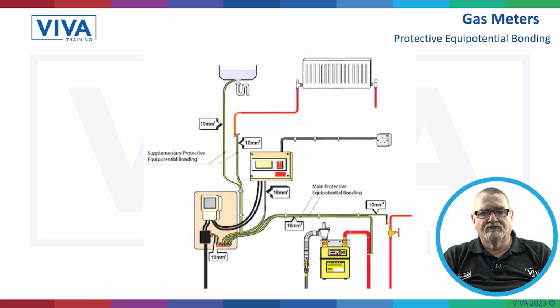And it says where practical, the protective equipotential bonding protects the installation within 600 millimetres of the meter outlet union or at point of entry to the building if the meter is external. So it could be in the meter box, it could be inside, and the connection should be made before any branch, so any T. It's got to be no more than 600 millimetres from the meter and before the first T. They're the important two points to remember about equipotential bonding.